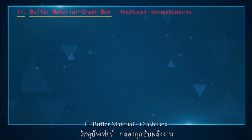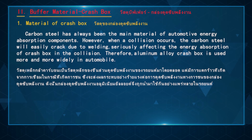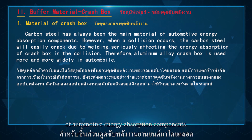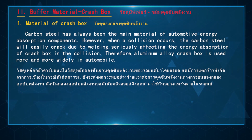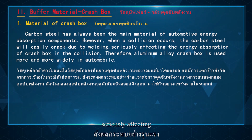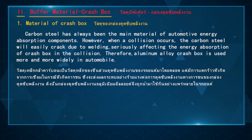2. Buffer material, crash box. Material of crash box. Carbon steel has always been the main material of automotive energy absorption components. However, when a collision occurs, the carbon steel will easily crack due to welding, seriously affecting the energy absorption of crash box in the collision.